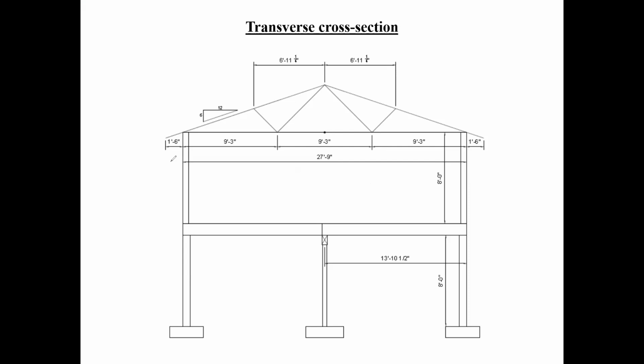So regardless whether the lintel is here in the back of the house or at the front, as far as the tributary width going in one direction here, they're all the same. So that's the tributary width that is being supported by that lintel, and that's exactly the same tributary width that's being supported by that window. So that's what you have to keep in mind.